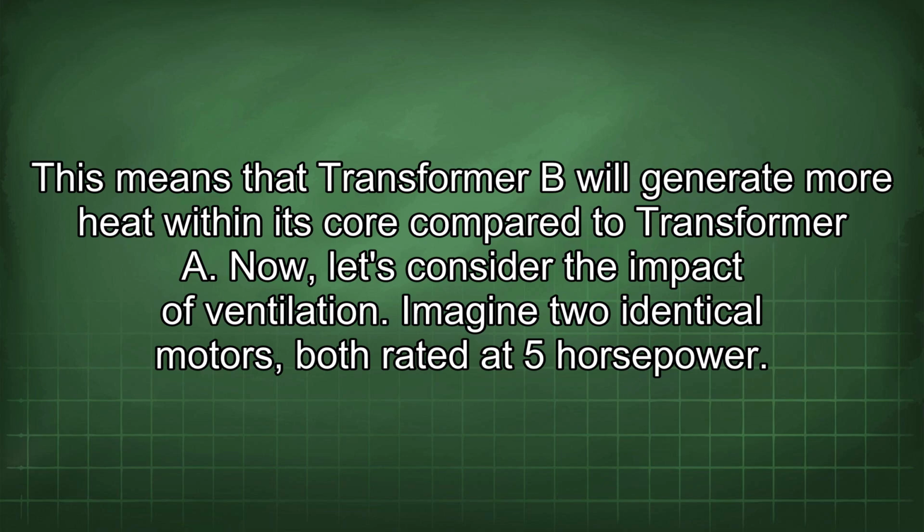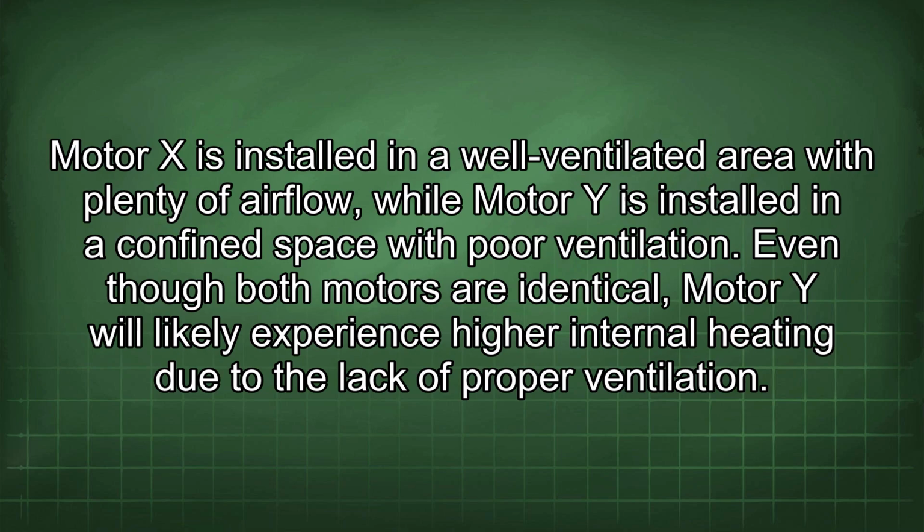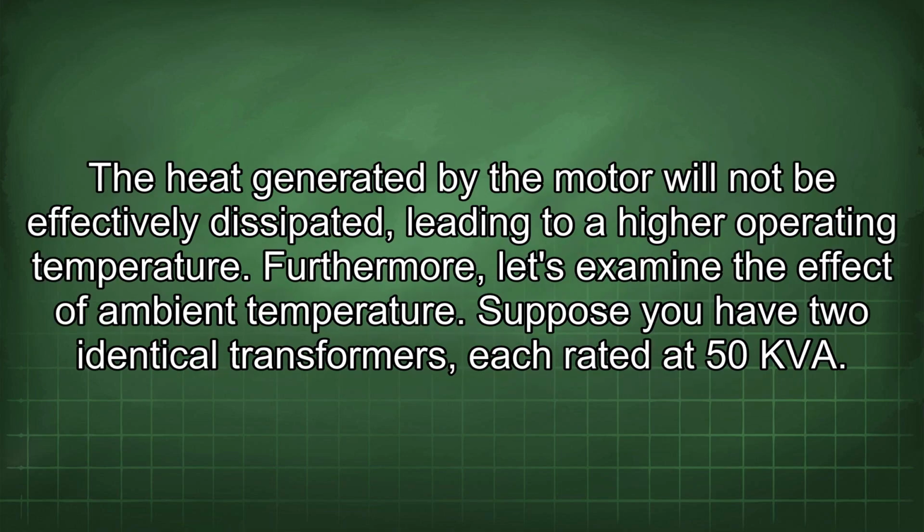Now, let's consider the impact of ventilation. Imagine two identical motors, both rated at 5 horsepower. Motor X is installed in a well-ventilated area with plenty of airflow, while motor Y is installed in a confined space with poor ventilation. Even though both motors are identical, motor Y will likely experience higher internal heating due to the lack of proper ventilation. The heat generated by the motor will not be effectively dissipated, leading to a higher operating temperature.